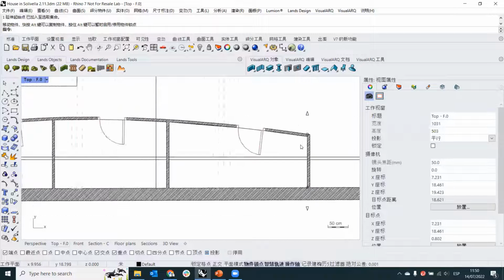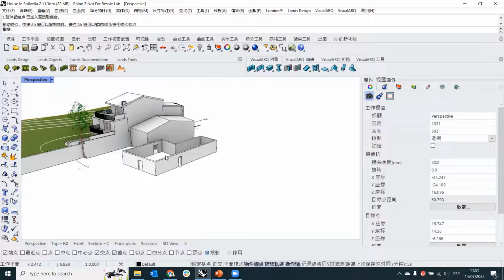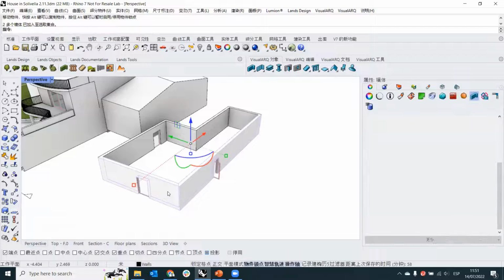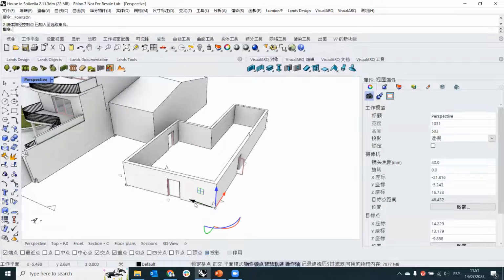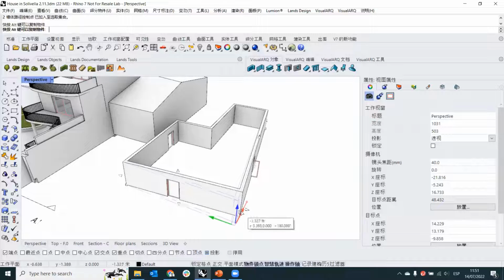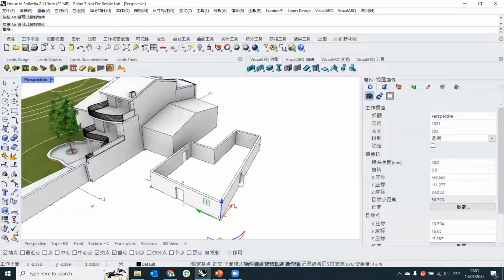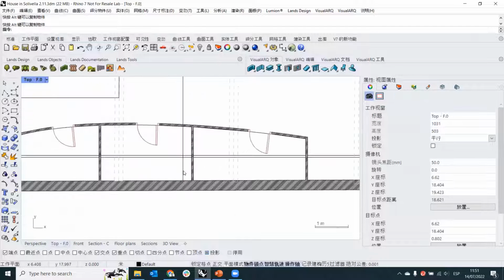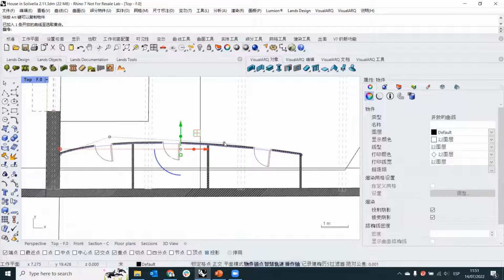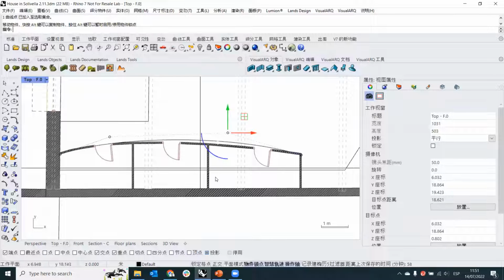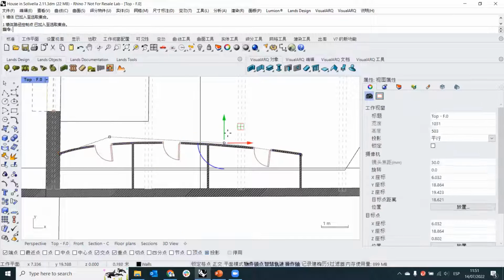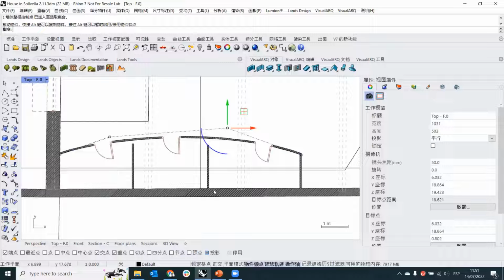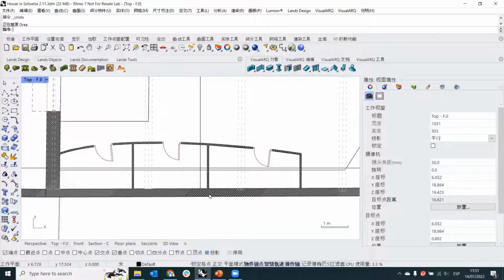So basically, walls have different control points that let us edit their positions. We have these extension arrows, but we have also some points at the bottom to stretch them in any direction. Okay. And in the case of walls created from curves, the control points are the same. Sorry, I was editing the original curve, but the control points are the same as the original curve. Okay.